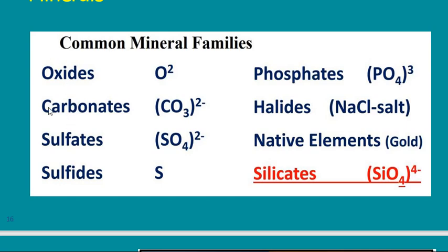But if the sand is related to carbonates, it means that there is something called leaching of carbonates. You put your building on top of carbonate sand, and maybe after 10 or 20 or 30 years, it will react or disintegrate, or there will be some kind of reaction and the volume will diminish.